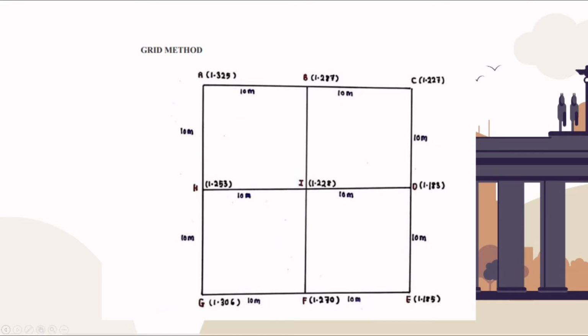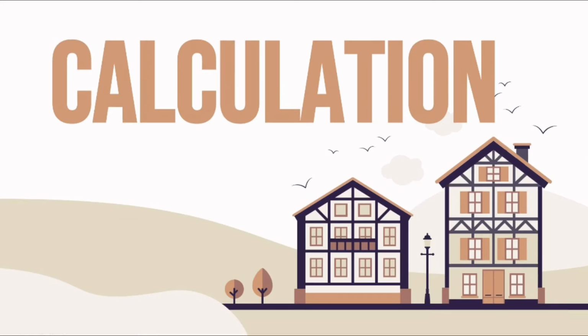The grid method of calculation involves drawing a grid onto the plan for the earthwork project. For every node of the grid, we set the value and proposed formation level and calculate the cut or fill required. Once the cut or fill is calculated, multiply it with the depth using the proportion of the grid cell. Do this for every cell of the grid, then add the volumes together to decide the general cut and fill volume for the project.